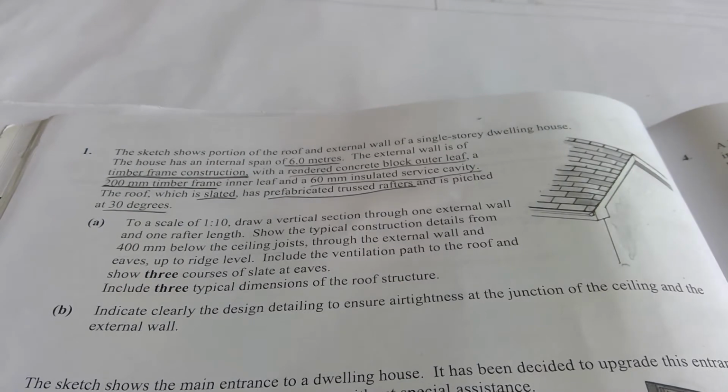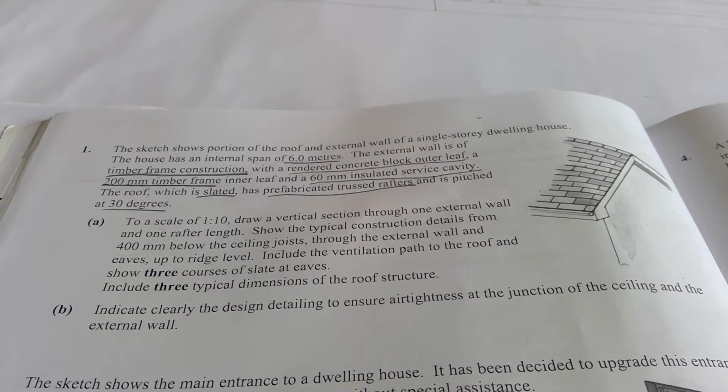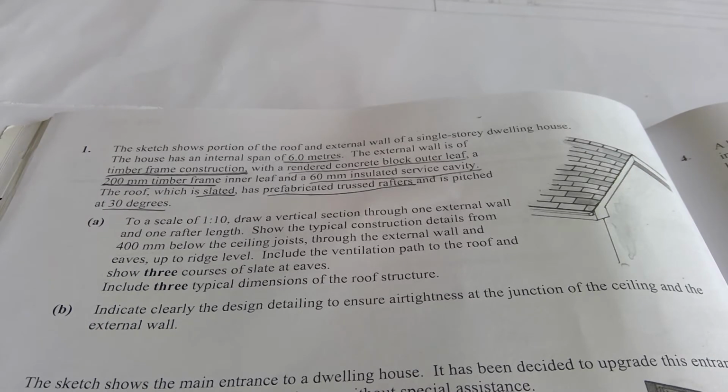Prefabricated trusses. For anyone who forgets, there's 2 types of building a roof. There's a traditional cut roof. That is when you cut the roof, all the pieces of wood, the rafters and the joists, on site and nail them into place. And the prefabricated truss method is when the trusses are made in the factory and they're delivered and they're lifted up with a crane and fixed into place. When it comes to a timber frame house, it will always be a trussed roof because you can just rest the trusses on top of the timber frame.